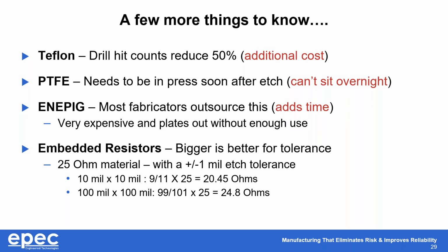We just point this out because it's a newer technology, and if you're trying to get better resistors, the larger the better from a yield perspective, because each one of those resistors gets tested at electrical test. So the bigger you can make the pad, the better it is for us from a cost perspective, because we're not going to have to factor in so much yield.